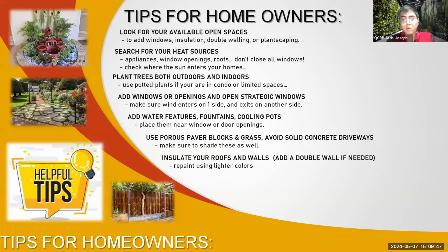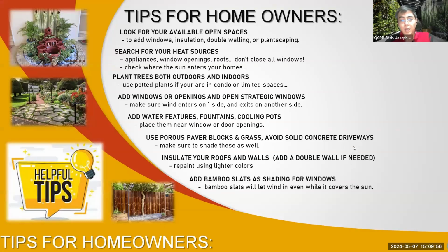Then, insulate your roofs and walls. Add a double wall if needed, no? Repaint using lighter colors. If you don't have the budget for the insulating paint, at least lighter colors, no? Add bamboo slats as shading for your windows. Bamboo slats will let wind in even while it covers the sun, no?